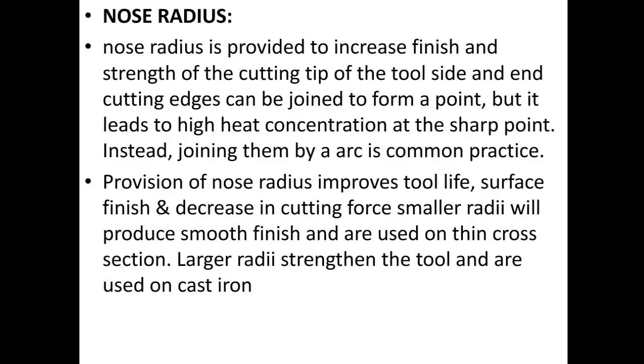Nose radius. Nose radius is provided to increase finish and strength of the cutting tip of the tool. Side and end cutting edges can be joined to form a point, but it leads to high heat concentration at the sharp point. Instead, joining them by an arc is common practice.